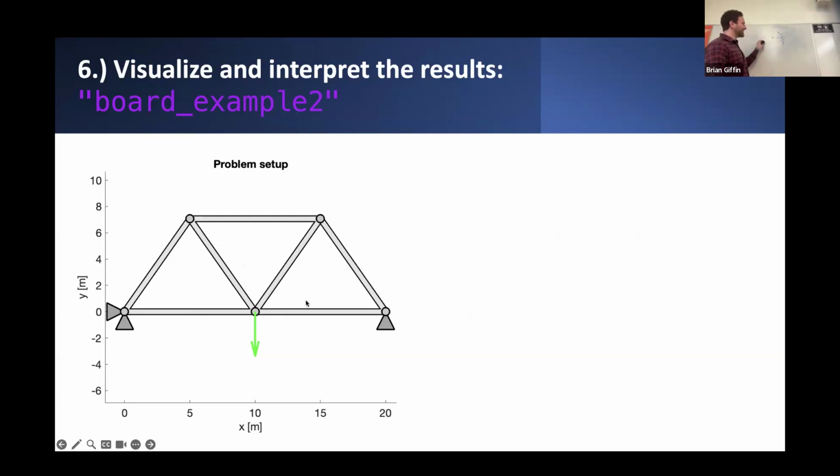Well, let's try good old statics, right? This is probably a good refresher. If we're looking at this bottom joint, we have a downward force here. Ultimately, we've said that these are going to be tension, or at least that's our assumption. What would the force have to be in each of these two members if this joint is going to be in a state of equilibrium? You say compression? This is going to point up. Pointing up, yeah. So in other words, it's got to be in tension, right? And what should be the relative magnitude of each of these two different forces? The same or different?